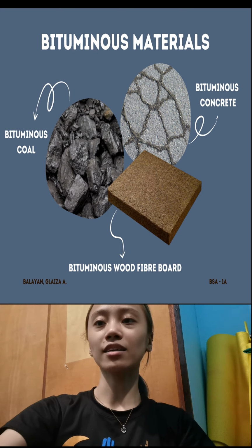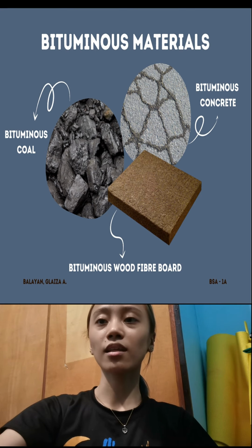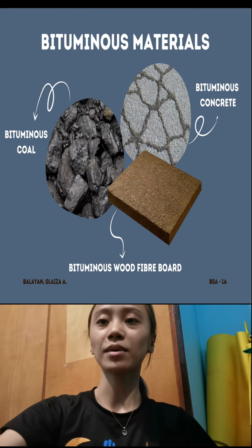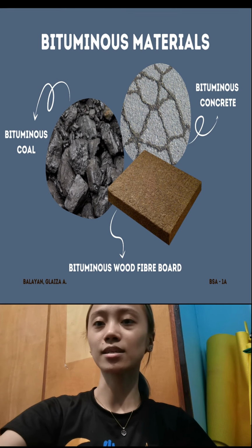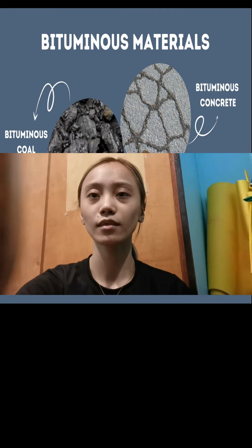Because of its relatively high heat value and low moisture content, its ease of transportation and storage, and its abundance, bituminous coal has the broadest range of commercial uses among the coals. It has long been utilized for steam generation in electric power plants and industrial boiler plants. In addition, bituminous coals that contain a fairly small amount of sulfur and cake easily are the only coals suited for making metallurgical coke, a hard sponge-like substance of almost pure carbon important for smelting iron ore.